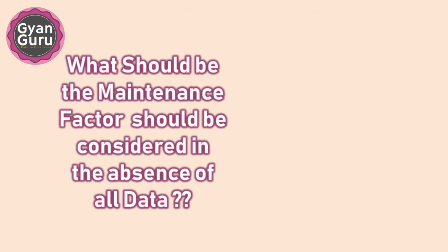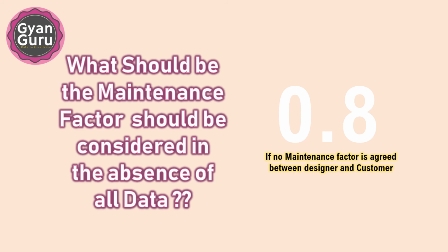What should be the maintenance factor to be considered in the absence of data? The maintenance factor shall be agreed between the designer and customer at the outset. This shall include the planned maintenance program on which the maintenance factor is based. If no maintenance factor is agreed, a value of 0.8 shall be used.